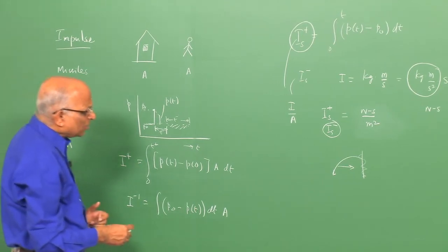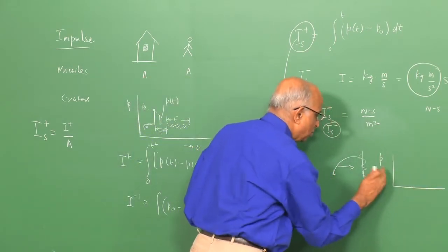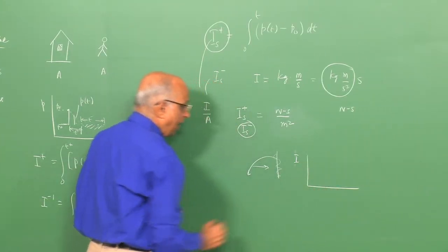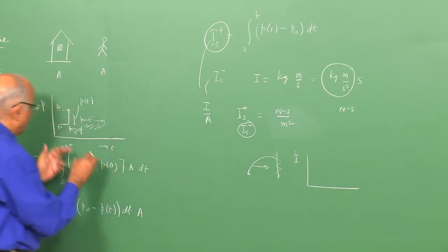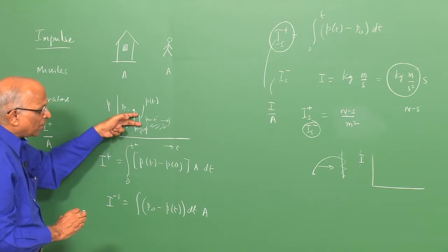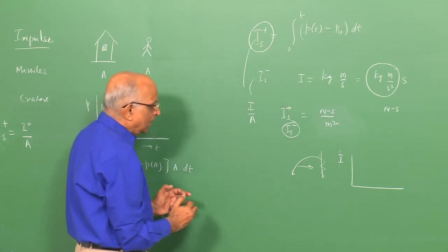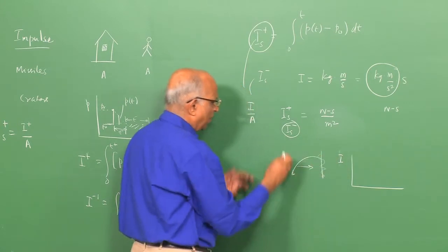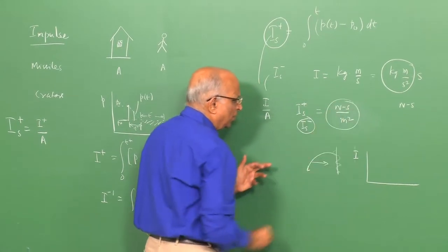Having said that, let us also take one more look. We are talking in terms of the pressure distribution, which gives me the value of impulse, and the impulse is over a particular time over which the blast wave is moving, or over which I have the positive contribution of pressure. Now, there is something which we must not forget. When we are talking of these impulses taking place, let us take a look at what causes this impulse. Is it possible to write the value of impulse? This is in units of Newton second per meter square.